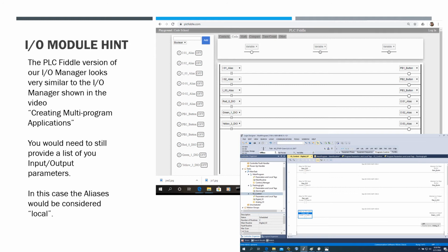Now, I will say that the subroutine is relatively simple. And if you are wondering why I'm putting the hardware I/O in a subroutine, I would assume that when you had PLC2, you would have gone through a demonstration where they showed you that when you exit a subroutine, whatever state an output is in, it can get locked.